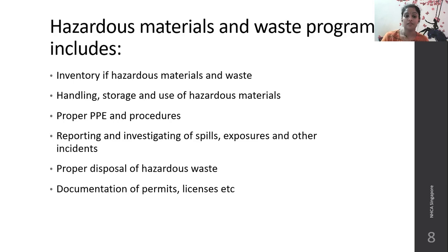Hazardous material and waste program includes inventory. The inventory for the hazardous material and the waste should be kept proper and regular inventory audit should be done. Handling and storage and the use of hazardous material should be recorded as and when it is used and who is handling it and who is responsible for using, storing, and handling the hazardous material. Proper personal protective equipment and procedures should be followed before handling hazardous material.